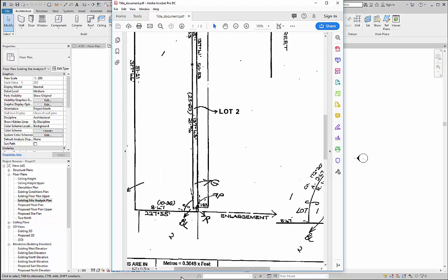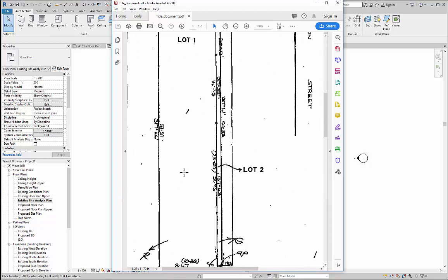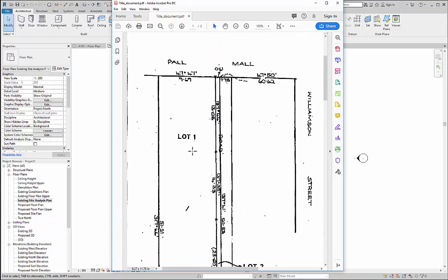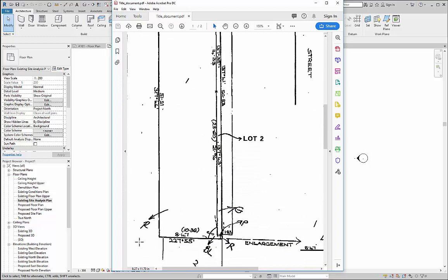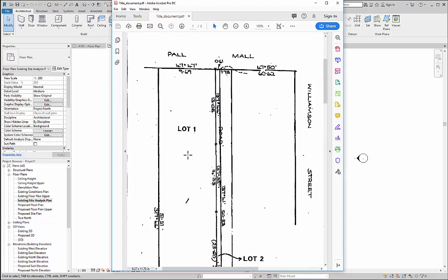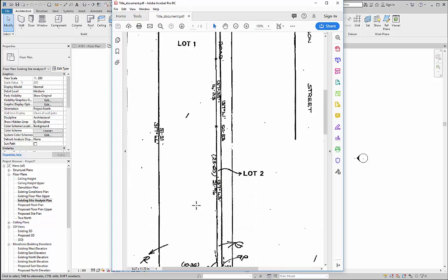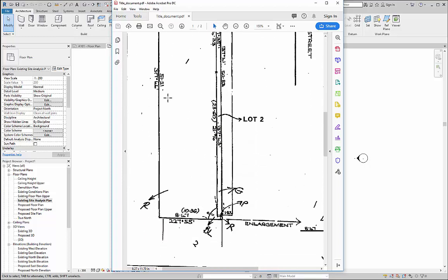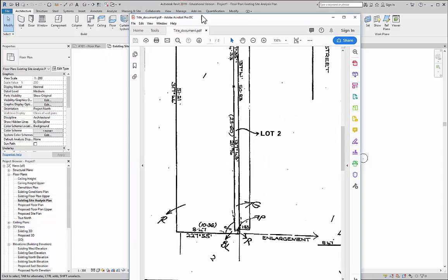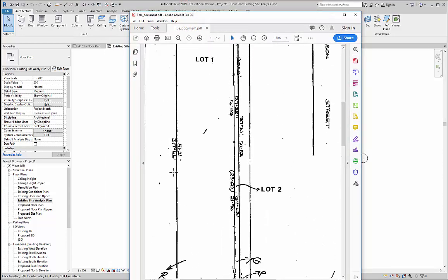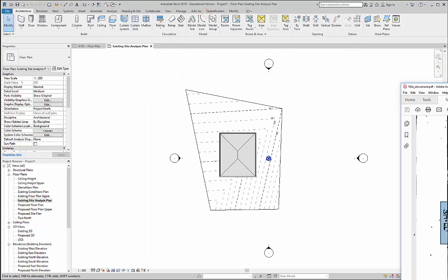So let's draw up this title and rotate to true north. When you're drawing a title document, never start at the front street, always start at a back corner. So if it doesn't close, it's not causing issues at the front where we are. For this project, we'll be building on the boundary. It'll need to be surveyed by a licensed surveyor anyway. Okay, so I'm going to start in this back corner, and I'll just drag this off screen, but I'll be inputting the data as I go, starting with the 5121 at 317 degrees 47 minutes.